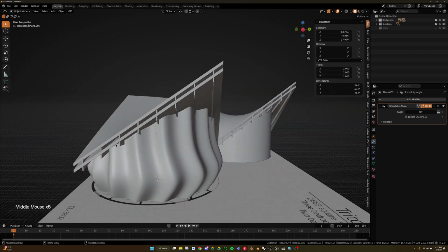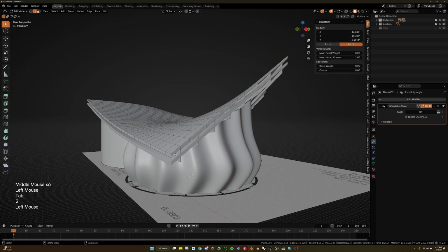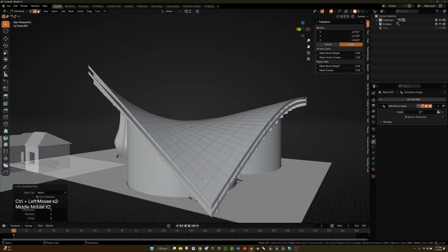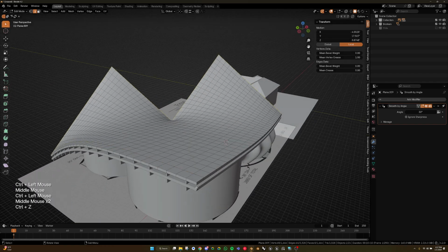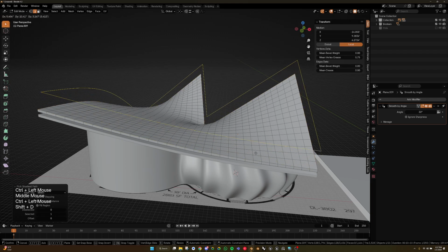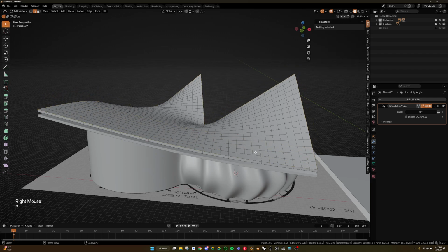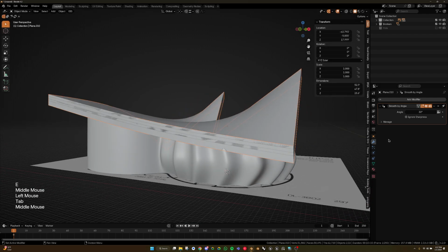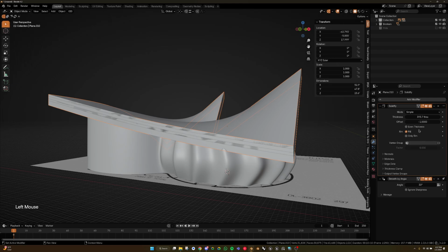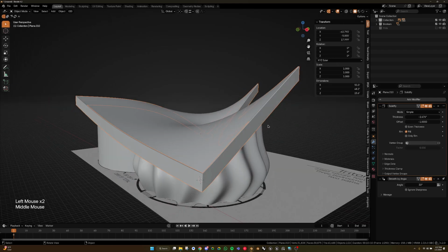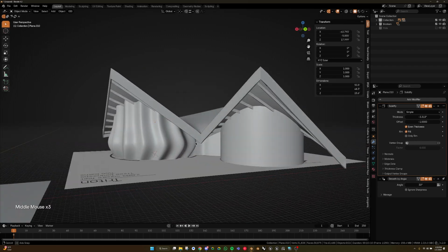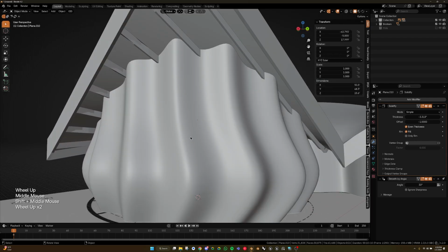And then if you want to have something along here, you can just take this edge, all the edges. So I'm going to hold Control, select all the edges around it, like that. Duplicate, separate by pressing P, selection, select it again, just extrude it down. There's your siding, solidify, look at that. There's your wood pieces that go along the outside to cover it. It's like your sideboard, or whatever, fascia. There you go.